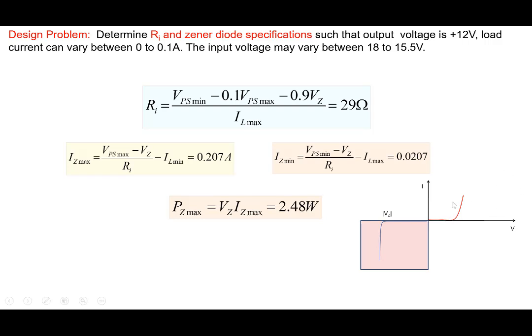And if we had taken a more detailed model of the Zener diode, then we would have taken the Zener resistance also into account here, and we could do a more realistic design, but it would become slightly more complex. But this is an initial design that we can obtain by following this particular method. And as we discussed, we can take an initial design and then simulate it, and do some fine-tuning based on the results of the simulations.